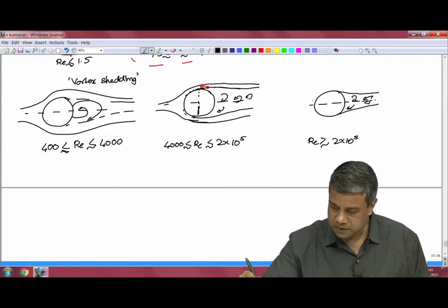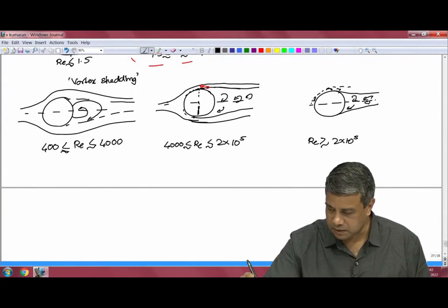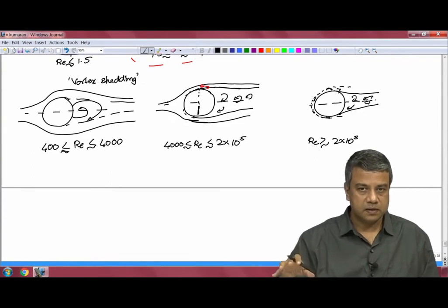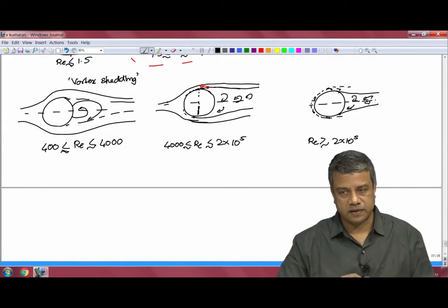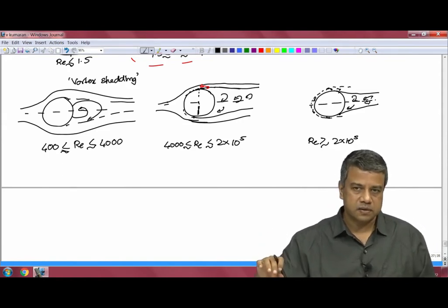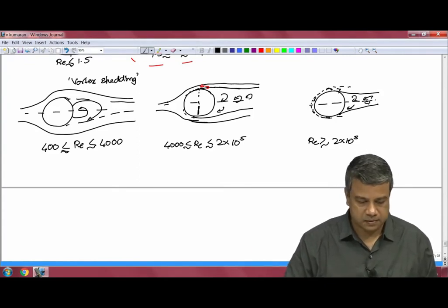And there is turbulence on the upstream side also, where the fluid is incident on the particle, what is called the boundary layer region, similar to what we had for a flat plate. The boundary layer on the upstream side also becomes turbulent, similar to what we had in the case of a flat plate. The wake region shifts suddenly to the downstream location, and there is turbulence in the downstream wake as well.